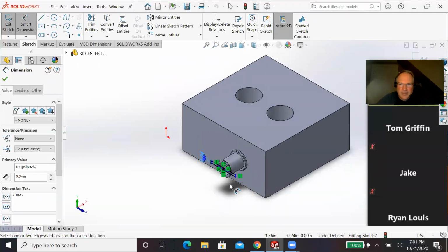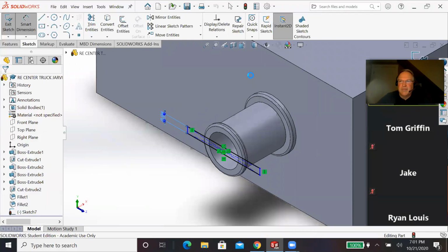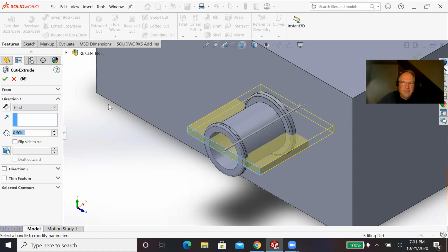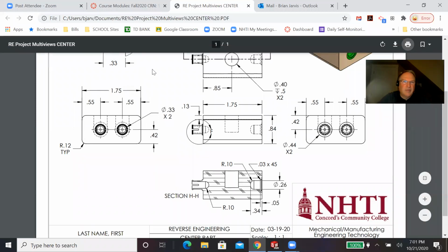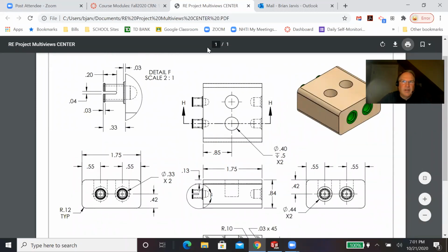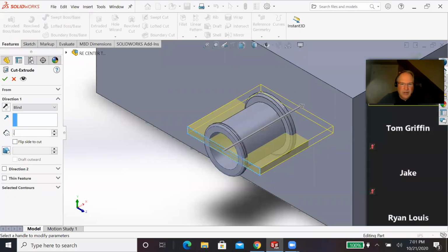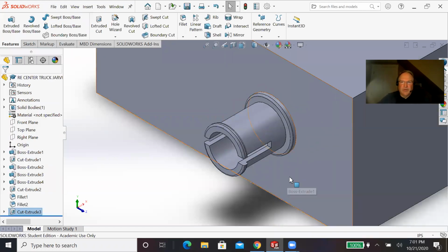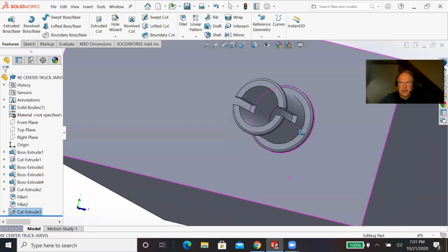Moving ourselves around a little bit. And then I'm going to go back. I'm going to finish my sketch. Extrude cut. Cutting into it. Must have a depth here somewhere. 0.2. Cuts in at 0.2. And check. So what looked to be pretty difficult, actually, if you use that center point rectangle, ends up being pretty straightforward.